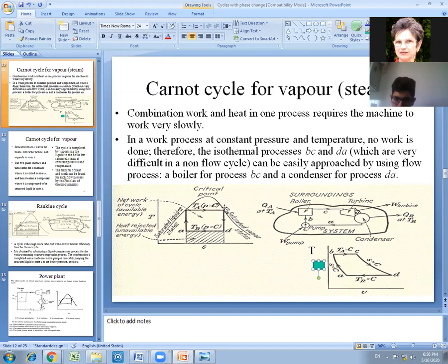This is an expansion, CD, this vertical, adiabatic process. And the turbine transforms the energy received from the vapors into mechanical energy that goes out. And normally it puts into motion the electric generator. And that's why the first result of the cycle is electric energy. So we start here with an input of fuel energy, and the output is electrical energy.